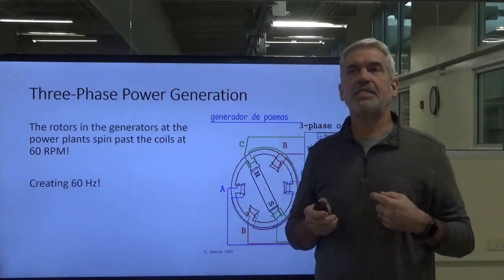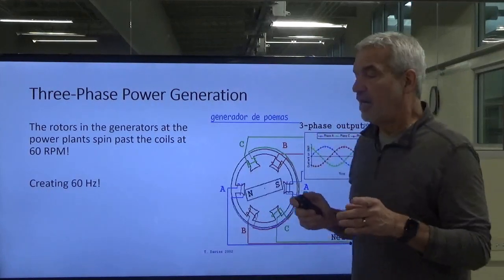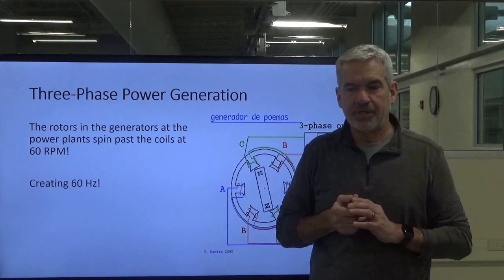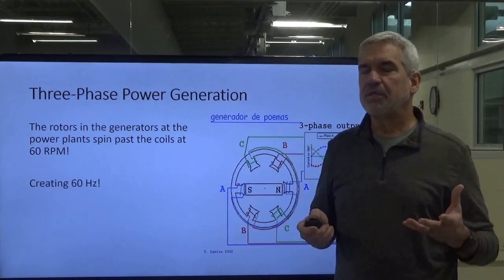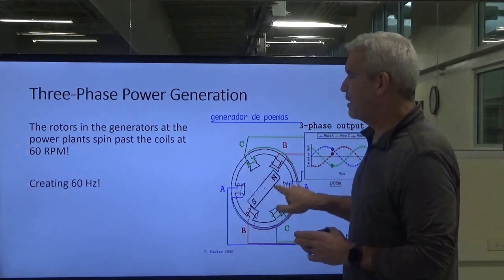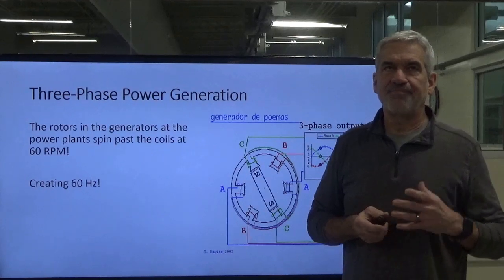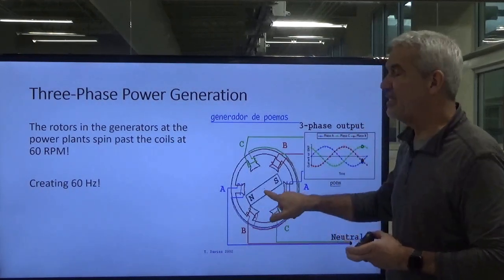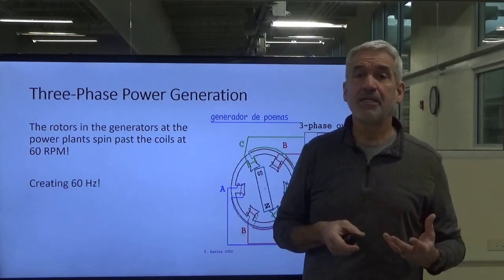If we didn't get the 60 hertz, a lot of our appliances would just be all over the place. Classic example, during the ice storm, there were some folks that I had come out and I hooked up generators, and it's hard to regulate the frequency of a gasoline-powered generator. There are so many factors that take away from how precisely it can deliver 60 hertz. A lot of times it'll be 65, 66 hertz, sometimes it'll be lower.